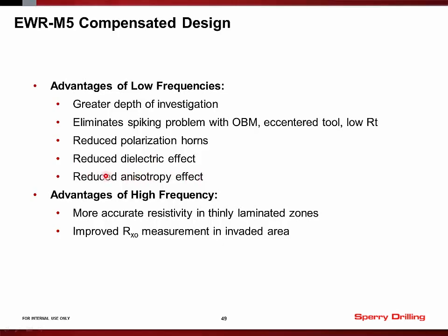Anisotropy also affects our measurements. I showed you an example of what that looks like earlier on. By reducing the frequency, we can also reduce the effect that the anisotropy has on the measurement.